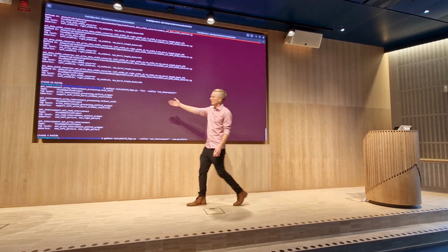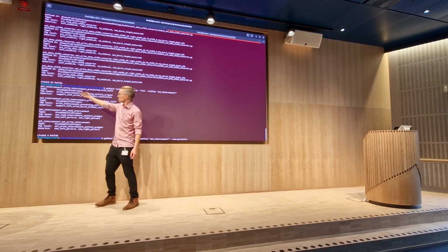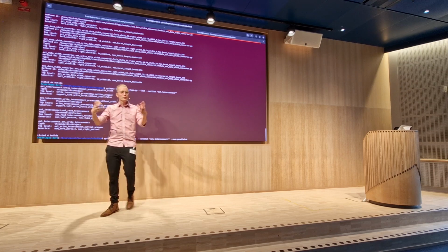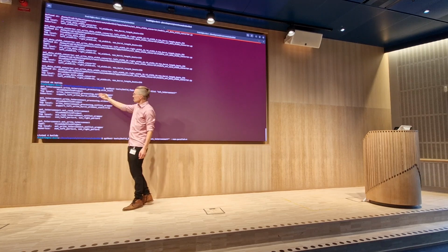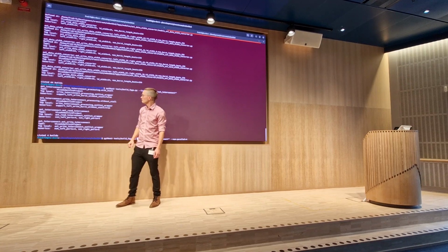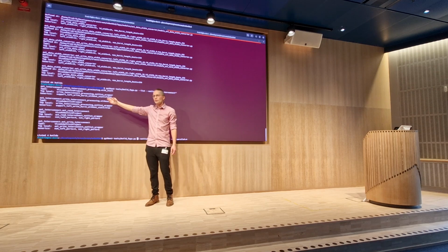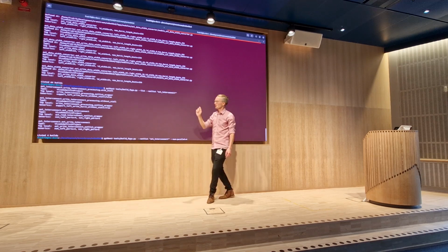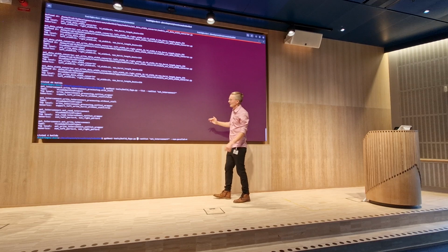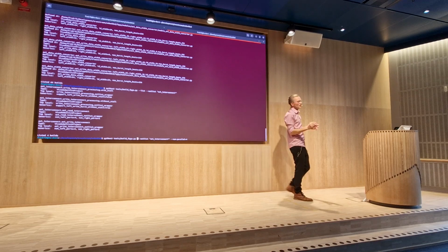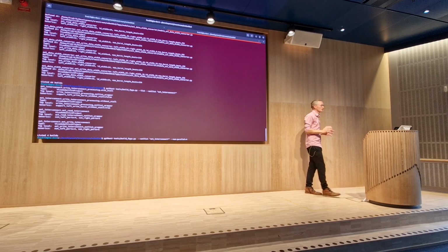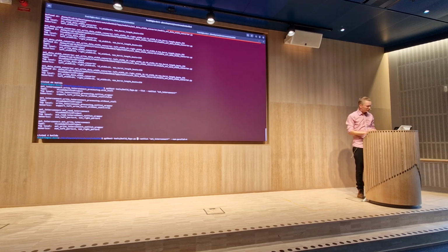You can see the information here, what kind of project it is. This is a Vivado netlist project. It's just a normal Vivado project if it's a normal FPGA build. It says top level and generics. For our FIFO, which is open source, and I'm going to show you a link later, we have a lot of generics, so the name is this long. And obviously, if we make small changes to that one, we need a way to control it, but all the configurations are always decent size. It's where this very much comes in handy.